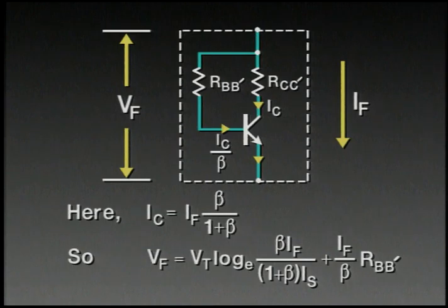Likewise, the collector resistance, although it's carrying the full collector current, appears in a branch where a small amount of voltage drop is tolerable, unless, of course, the collector junction goes into forward bias, which would correspond to the transistor going into saturation. We would avoid that by the use of a sufficiently small current in the collector, or, of course, the use of a transistor of sufficiently large geometry.